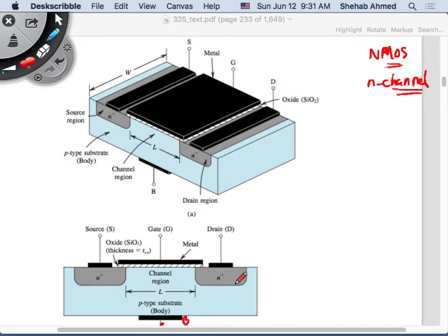Remember, substrates or semiconductor materials are constructed from a single material that is doped and does not react with anybody else in the environment because of all the covalent bonds. Remember that discussion? That material can be either N-type or P-type, right? So here we start with a big ingot, and then you chop it up, and that's called the wafer. Each one of those thin slices is called a wafer. So you start with a P-type substrate or P-type wafer for an NMOS, N-channel type device.